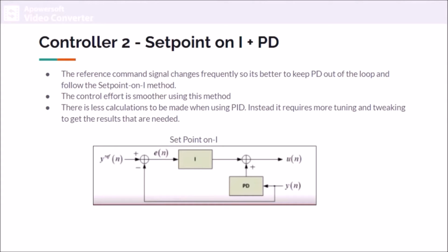So today's presentation, I'm going to present the second controller, the PID controller. PID stands for proportional integral derivative controller, which is basically a control loop mechanism employing feedback. It's widely used in industrial control systems, and it continuously calculates an error e(t), which is the difference between the desired set point and the measured process variable, and applies a correction based on proportional, integral, and derivative terms.